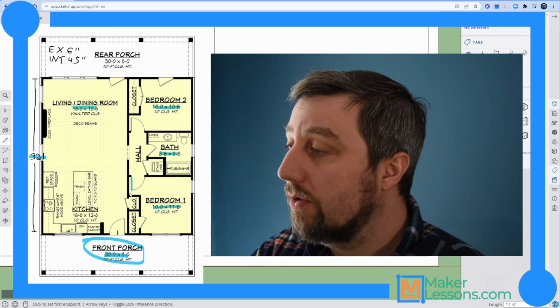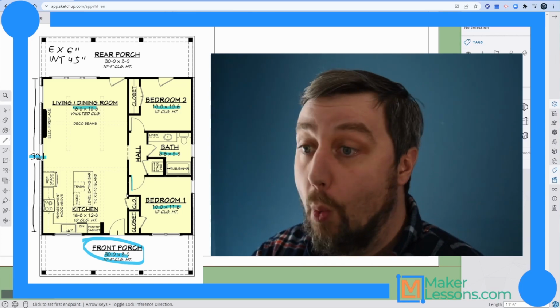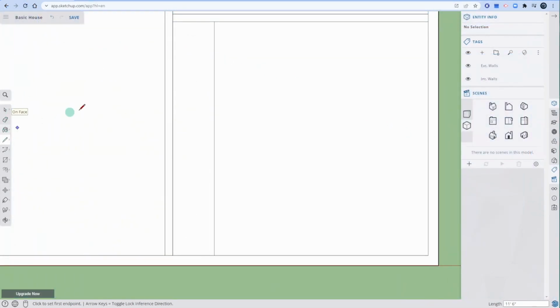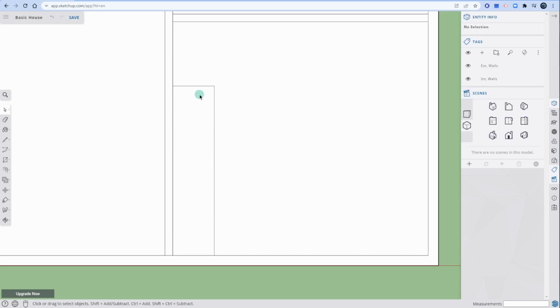If the door swings 32 inches, we want a little bit afterwards. Let's say that's 6 inches, so 38 inches. Why not? So I'm going to draw a line from here. I'm going to go down on edge, 38 inches, hit enter, mouse over, there's my endpoint, and I'm going to scoot this over, pow, beautiful. Spacebar, click on this edge of the line now, and now I can delete it. So this is our 2 closets in the corner there.